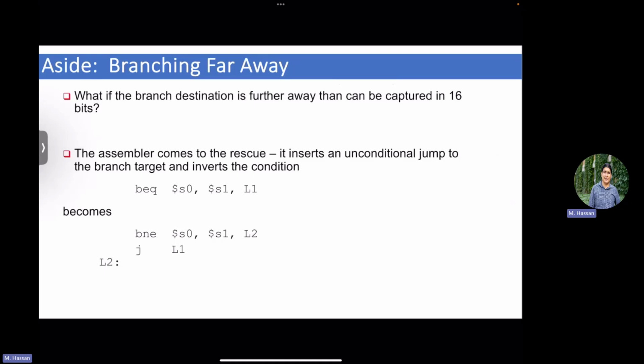First of all, why does the jump to L1 work and why does the branch not? Why, if L1 is a very large value, does this one not fit while this one does? The idea? A jump has the longer address. So this one is 16 bits, right?